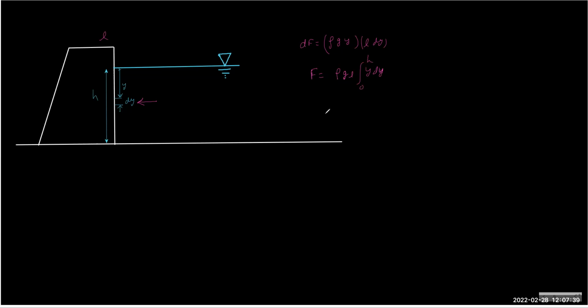This we can also write as rho g, integral of y L dy. Correct. And this we can also write as y dA, because L dy is called dA. Now this can be rewritten as, if I divide by dA and multiply with dA, it is the same equation. So we have a nice expression for force.